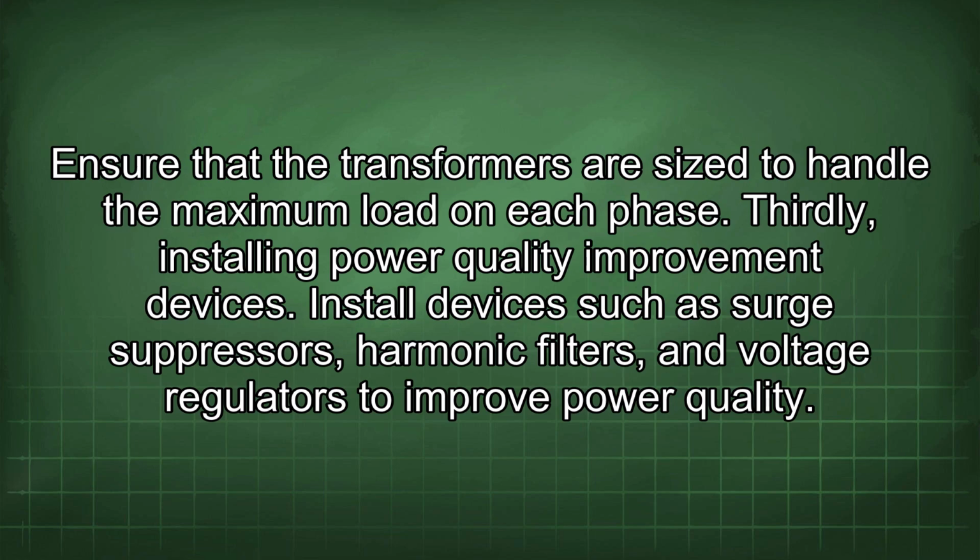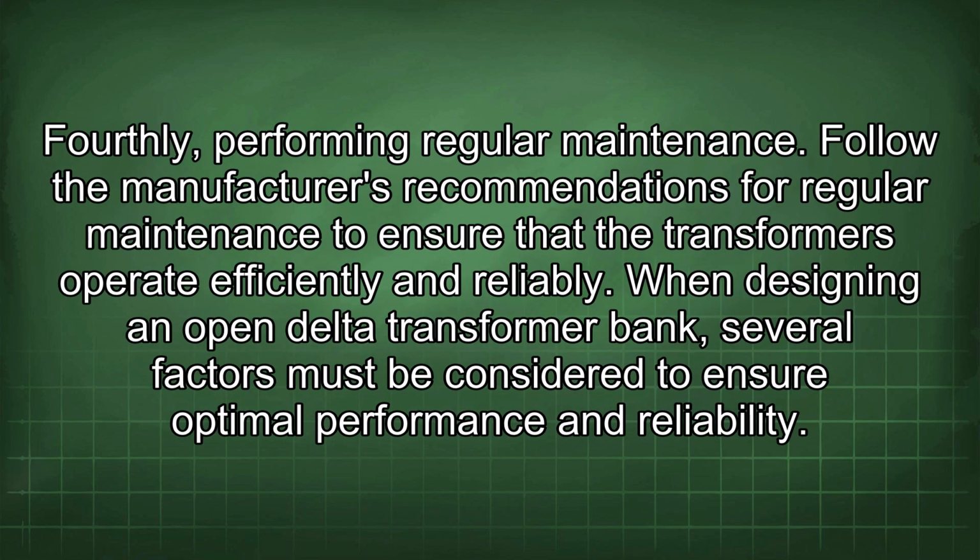Thirdly, installing power quality improvement devices. Install devices such as surge suppressors, harmonic filters, and voltage regulators to improve power quality. Fourthly, performing regular maintenance. Follow the manufacturer's recommendations for regular maintenance to ensure that the transformers operate efficiently and reliably.